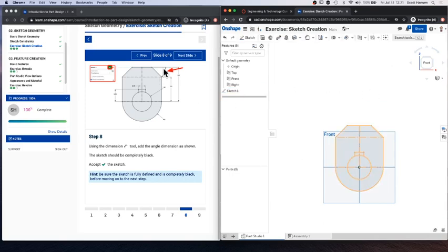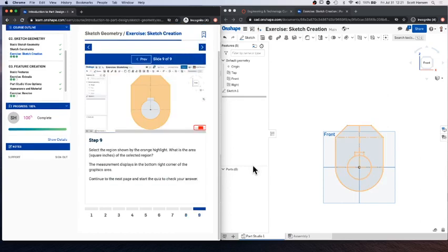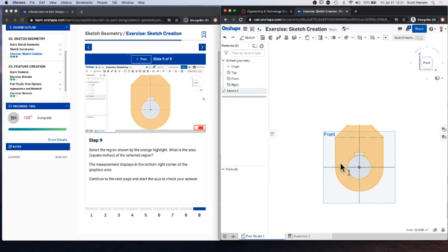One more thing before I let you go. Next slide. There are some tools here that'll help you get some information about this sketch, and this is part of the reason we want to use construction lines. If I click inside my sketch, it'll highlight the interior part of the sketch. Down in the bottom right-hand corner, there's what's called measurement information and materials information. Here I can figure out the lengths of things, area, and volume once we start working in 3 dimensions. We can set materials, so we can make this metal or plastic or whatever. If you click a line, it'll tell you how long that line is. If you click an area, it'll tell you what the area is.